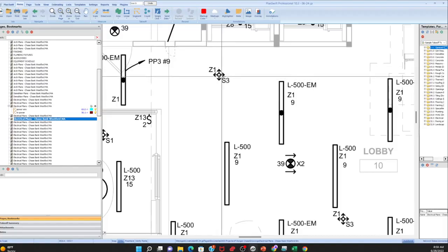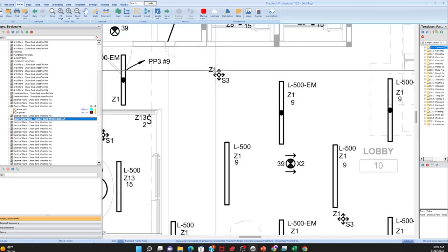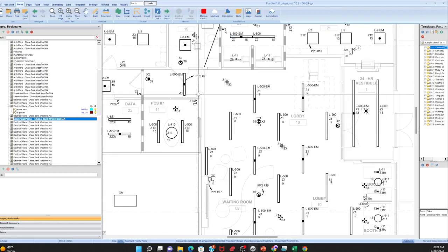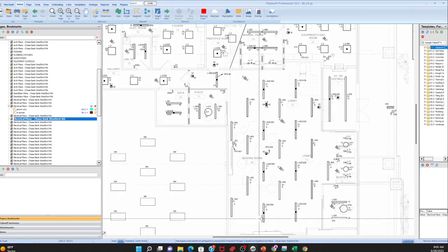So yeah, we're going to look at the symbols list in our lighting plan to tell us what that is. Okay, that's some kind of directional sensor. But then again, it's all connected to zone 1. So this tells the electrician all of these lights in this little area are zone 1 lights connected to, that 9 is actually probably a position in the lighting control panel. So just like the outlets, they all have the same number. That's telling the electrician that these are all connected to the same lighting control. And we're going to call it number 9. Okay?